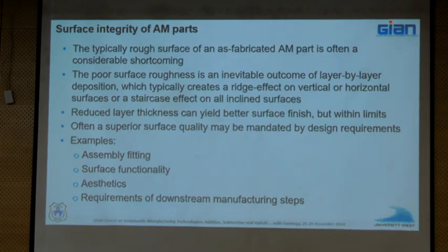So although you know that reducing layer thickness can yield better surface finish, it's two things. One, it is still not ready to be used for many applications. You still need something. And second, it compromises productivity. So reducing layer thickness is not a relief.